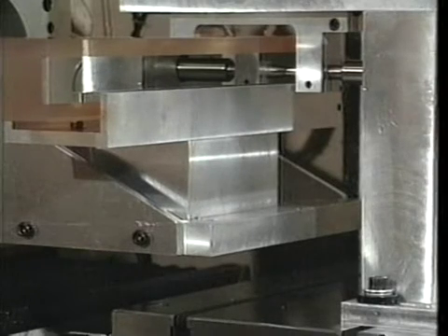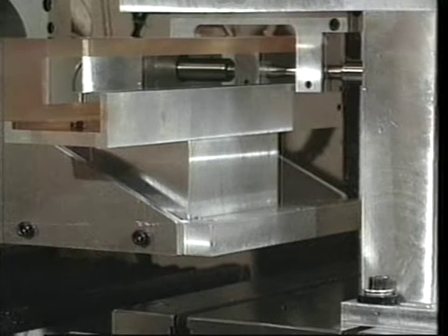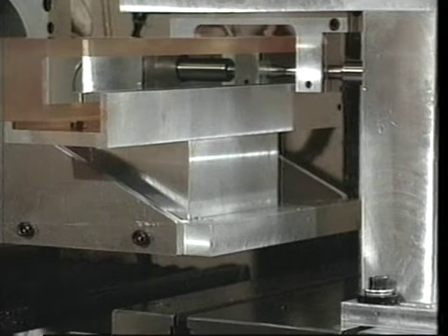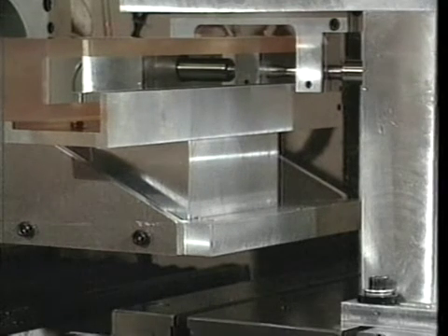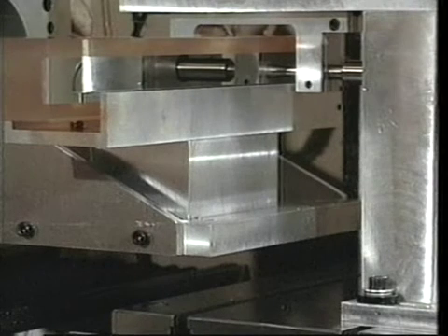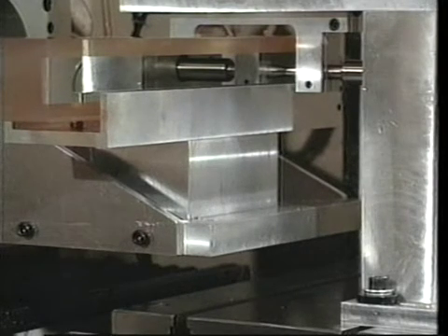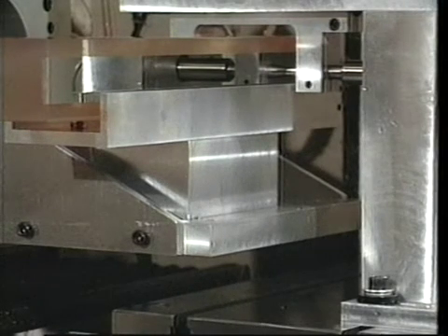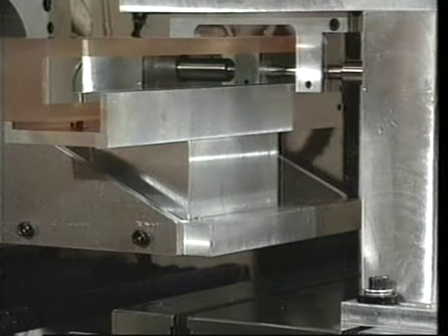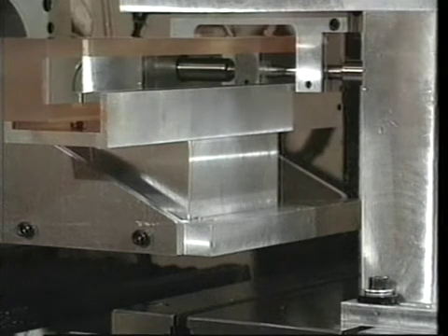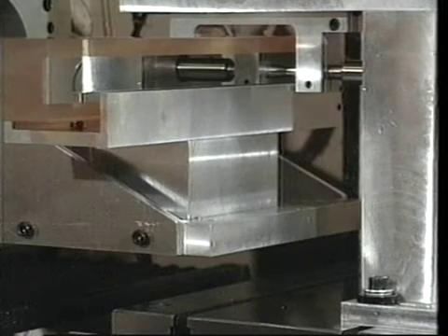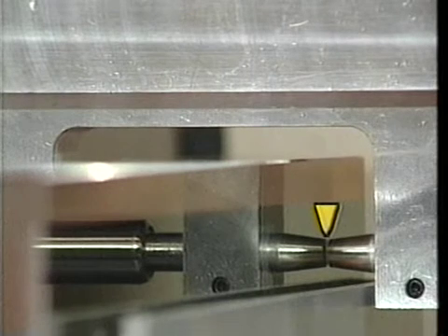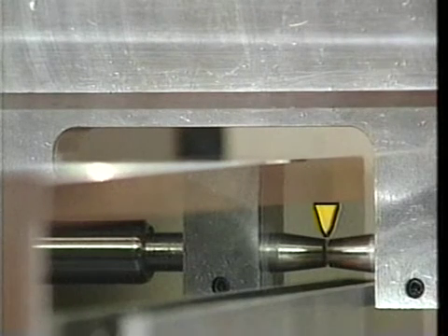Recapping the setup, the kinematic cradle is mounted to the stationary z-axis such that the horizontal center line of the straight edge coincides with the horizontal center line of the spindle. The holder for the capacitance gauge head is mounted to the x-axis, the carriage whose straightness is to be determined. The capacitance gauge head, or probe, is positioned in the holder's reversal yoke at the center line of the straight edge such that it senses changes in the separation between the probe tip and the reference surface of the straight edge.